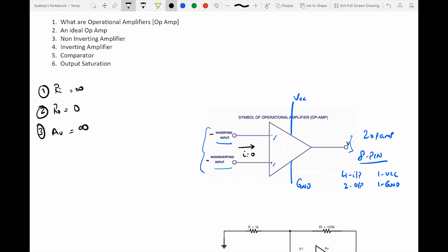The fourth characteristic states that the operational amplifier would try to have the voltages at the inverting terminal, which is V1 in this case, and V2 as equal. It would do its best, matching current flows and everything, such that the voltage V1 at the inverting terminal and the voltage V2 at the non-inverting terminal are always the same.